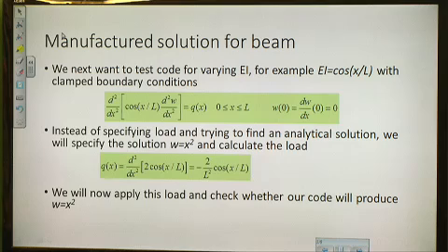So I decided that the way a skyscraper tapers may be captured typically by cosine of x over L, where x goes from 0 to L. Anybody can tell me what's the value of cosine of 1, approximately? Not 1 degree, 1 radian. 1 radian is 57 degrees. I'm hoping that some of you know what's the cosine of 60 degrees. I'm sorry? 0.5. So we are considering here a beam that loses about 50% of its rigidity from top to bottom.